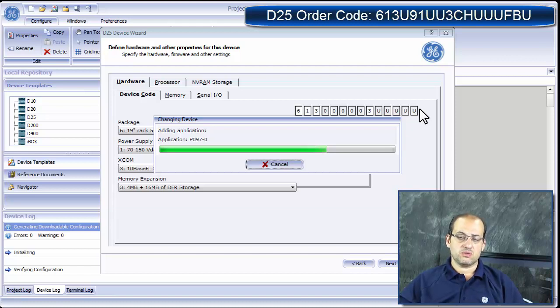So in the world of the D25, there are data collection applications and data processing applications. Data collection applications stands for basically client application. It works with all the field devices gathering information. So one of the field information that we're gathering is the physical points, the I/O card that's inside the D25 that I've shown you, and the application that takes care of the 3 digital input cards, the 1K card, is the plant I/O or P097, which is this application, right? It constantly scans these cards for an update on the points and the status of these points.